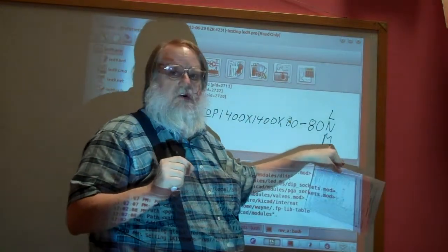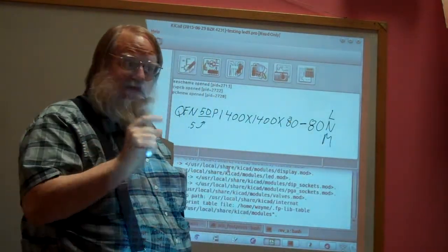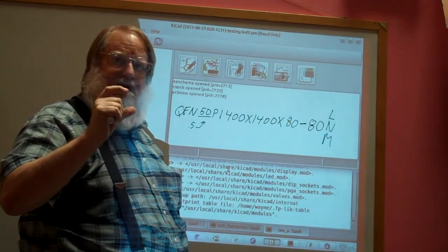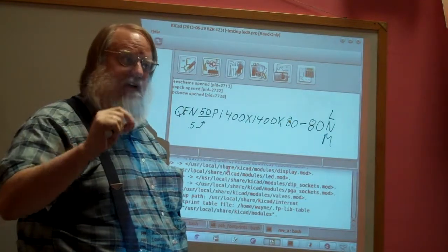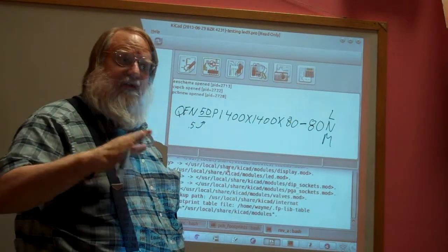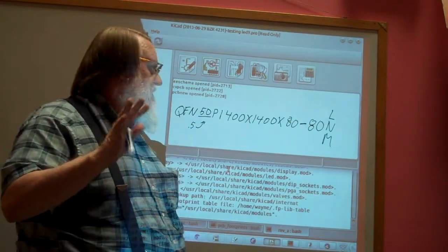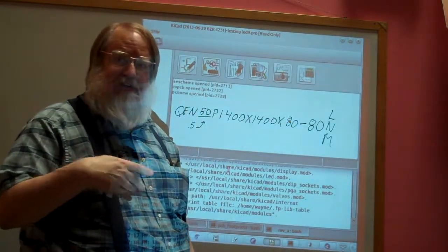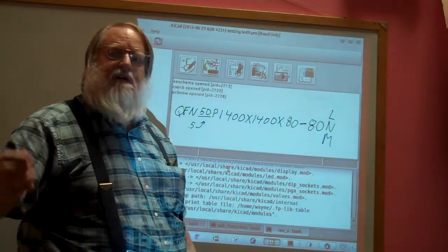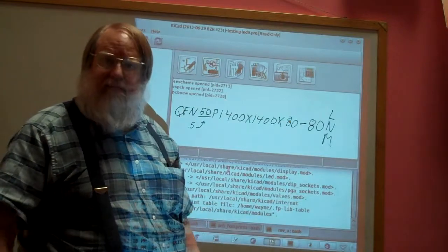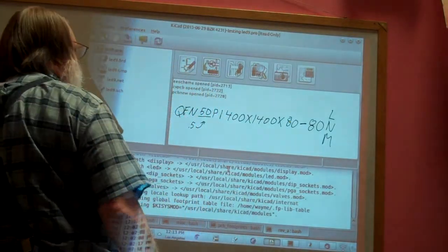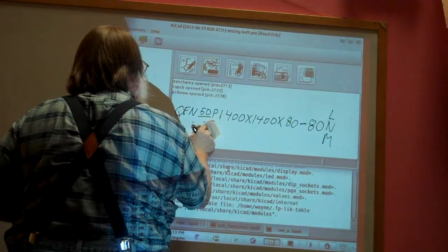M is what they use for aerospace. This is where they want as much reliability as they can get, so they want as much footprint area underneath the lead so they get really nice solder fillets that cover the pads. And then N is nominal, and that's what the rest of us use, which is fairly standard, not too big, not too small. So that's what a footprint looks like.